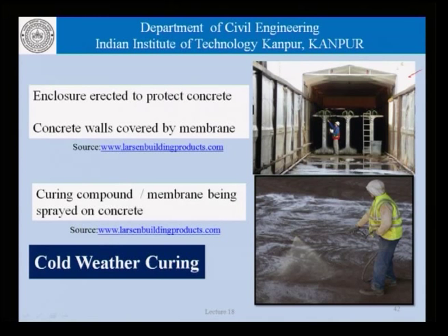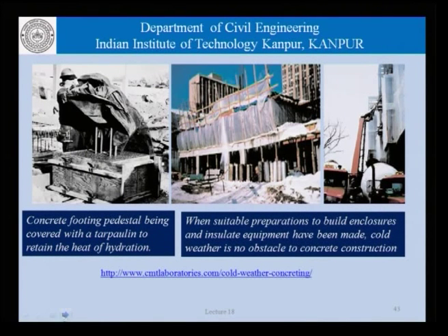This picture here, for example, shows an enclosed structure which has been erected in order to protect this concrete. Similarly, as far as these panels are concerned, we could see the covering of membranes. As far as this picture is concerned, it's just an application of curing compounds being sprayed on concrete to serve as effective sealants. The picture on the left hand side here is that of a concrete footing pedestal being covered with a tarpaulin to retain the heat of hydration.